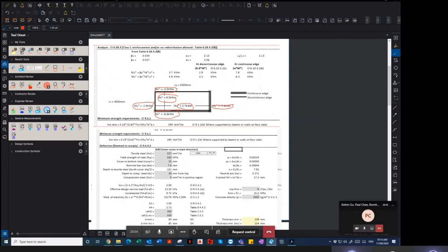For example, if you've done a steel column check, and roughly the capacity of a steel column, 89 by 89, we don't have to do that all the time. Once you've done it, you know how to do it, and most of the time in a small construction, like a 2-story house, it works.